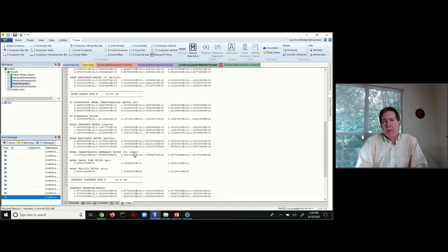In the theory material on 3-phase, I talked about the use of the Karrenbauer transformation to convert from ABC to the modal reference frame. Why am I bringing this up right here? Well, I showed you one transformation that could do that, the Karrenbauer transformation. But what PSCAD does in the T-line program is it takes all this 3-phase information and comes up with a custom transformation matrix. In this particular case, they talk about this modal transformation matrix.